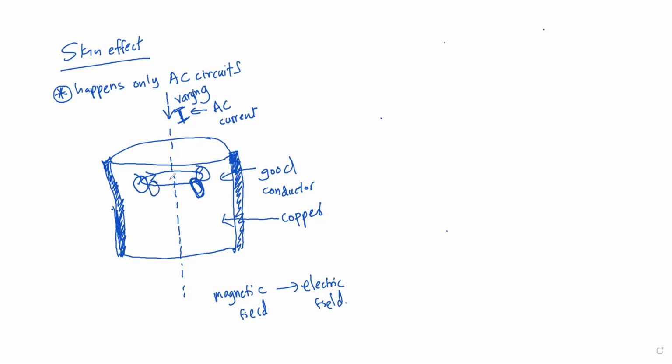So these eddy currents are getting more powerful once the frequency of the current that we produce using the alternating current is high. When we increase the frequency, the amount of magnetic field variation also increases, and because of that, the amount of eddy current generation also increases.